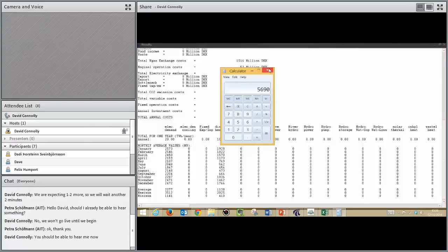So if you ever are carrying out some scenarios for the future and you want to design some new district heating systems, then these are good rules of thumb or indicators of what range of boilers and thermal storage capacities you can start your analysis with. Of course, you can then analyze these different capacities to see which makes the most economic sense and so on, but at least you have a starting point when you use these thumb rules.